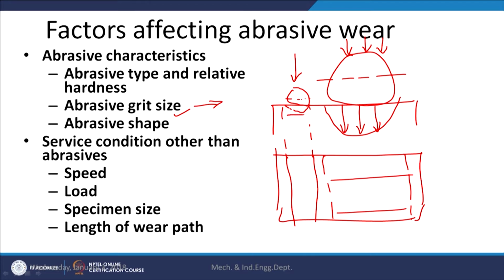So, the penetration depth is small for a fine particle, while in the case of coarse particles the depth of penetration is more, and that is why in the initial stages the wear directly increases with the abrasive grit size, especially under low load conditions. Why it is about low load, I will talk about now.